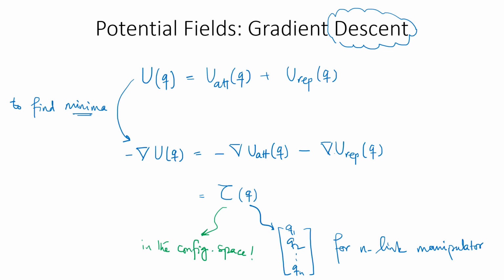We define the link initially with this basic idea, just like a point-represented manipulator. But actually the manipulator is going to have a body, it is going to have links. So there are going to be potential collisions between the obstacles and the links of the manipulator. That's why we are going to define the potential fields in the workspace.